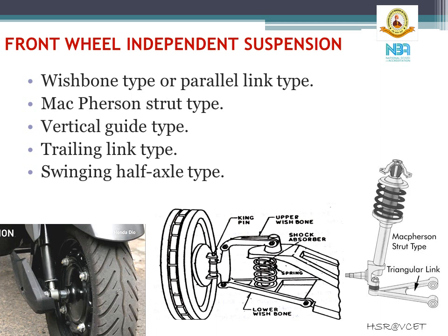To avoid this, wheels are sprung independently of each other so that the tilting of one does not affect the other. Other than this, there are several advantages over rigid axle type suspension, such as increased tire life. Lighter springs can be used in case of independent suspension. Soft springs improve ride comfort. Etc.